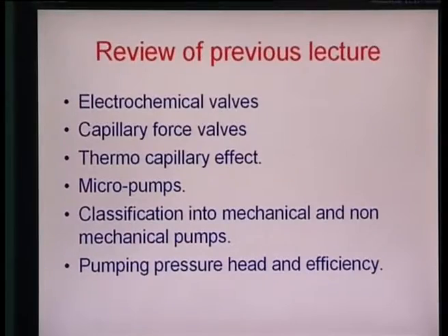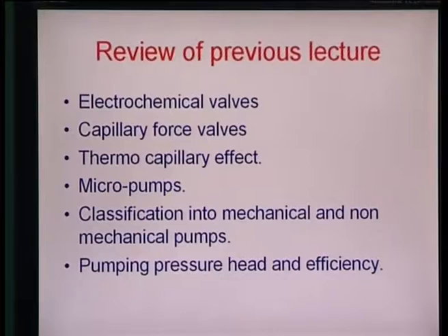Therefore the pumping efficiency is the ratio between the power required for pumping divided by the power required for actually actuating the micro pump. So essentially, it is a ratio between the power generated by means of flow and the power supplied into the system. So this is as far as last lecture goes.